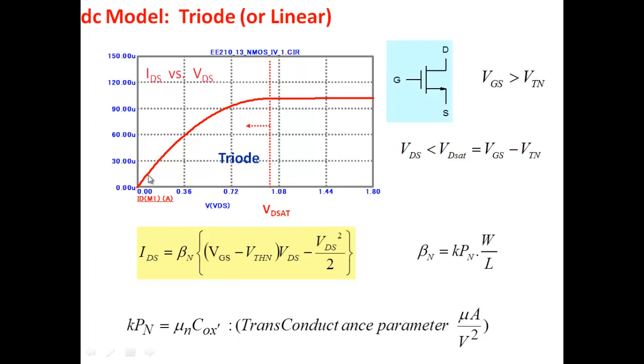The value of the resistance you can control by applying different amounts of gate to source voltage. So think of MOSFET as a resistor here, which this particular equation is sort of telling you. Of course, if you go beyond that, then it's no longer like a pure resistor, but a nonlinear resistor it will become. All right, so this is the equation, very important equation, that if I am in this region, then this is the equation that I use to understand my MOSFET operation.